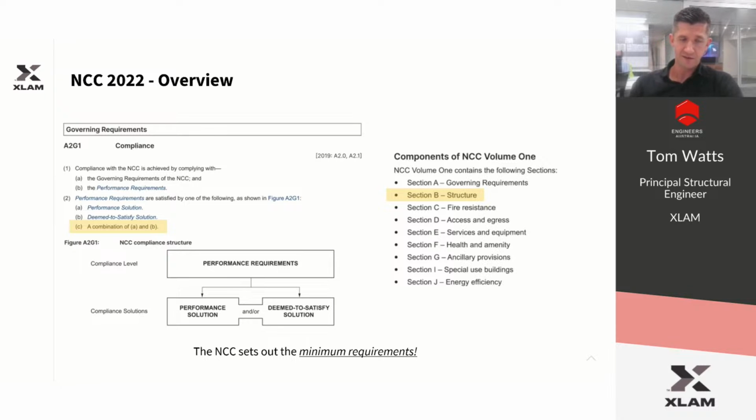Most commonly these are the connection details for the variety of different connections that we're looking at with mass timber. Most of these will either need to be considered with design information coming from the European Timber Code, Eurocode EC5, or looking at the use of proprietary brackets, which will have capacity information covered under the European Technical Assessment pathways.